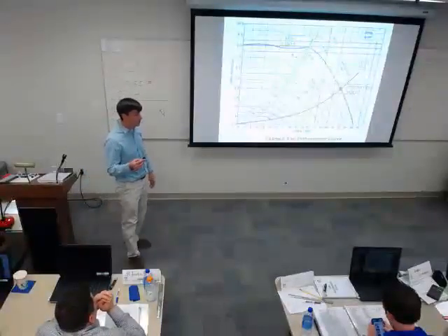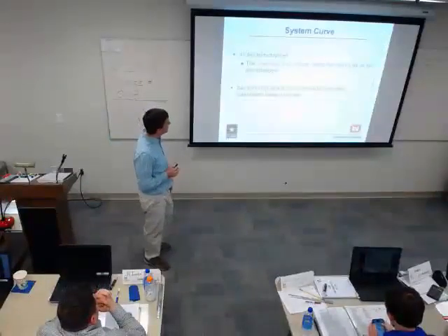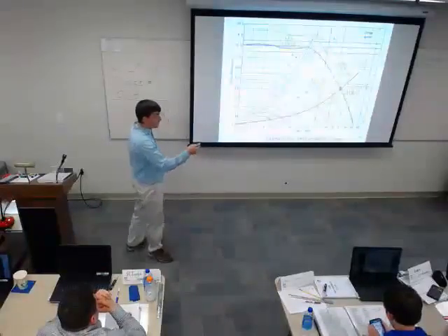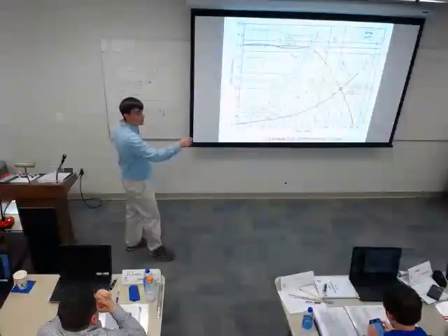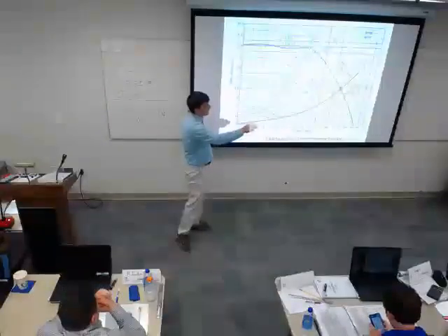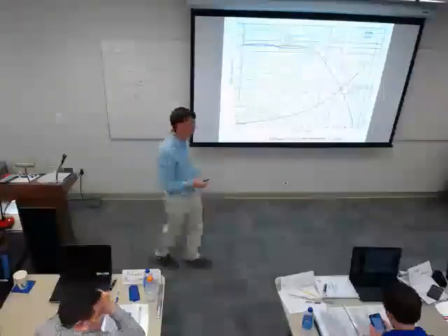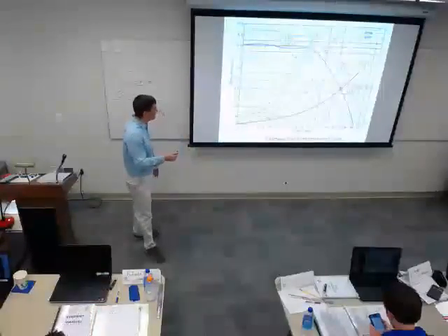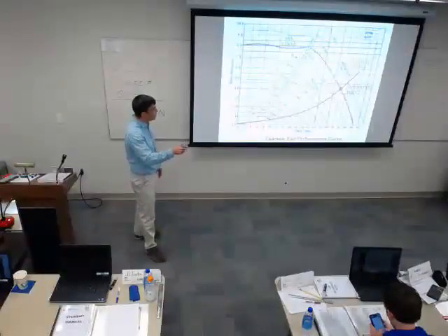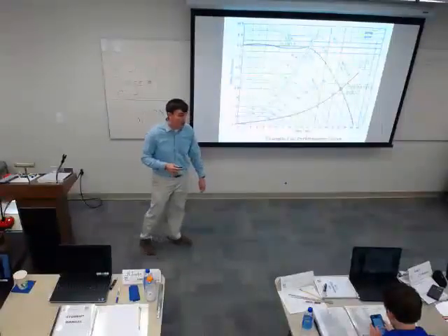Ask questions. Where did you get the operating point, the number 35? I measured the static pressure of 4 inches, and I gave you that my fan was running at 1300 RPM. Sorry, I probably need to add that to that slide. So in this example, the fan's operating at 1300 RPM, and I plotted from my measured static pressure over to whatever speed my fan was operating at.